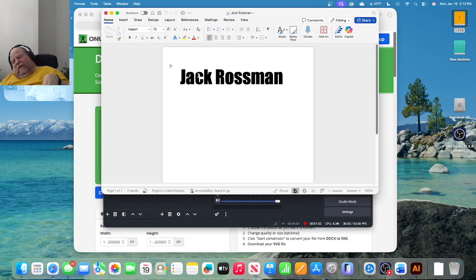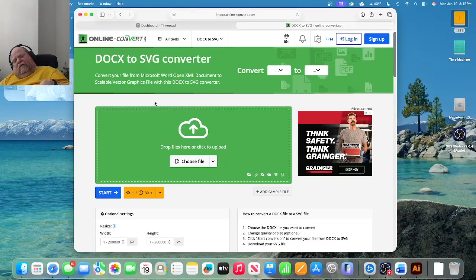So it can be whatever you want. It can be your name. It could be Tree or your buddy Michael Eichler or Mark Devine or whatever, Terrence, Judd, Randy, whatever your favorite name is. So we're going to save that. That is actually saved in my documents folder. The whole point is we want to take that Word doc, the docx file, and convert that to a .svg because you need the SVG format to import into TinkerCAD.